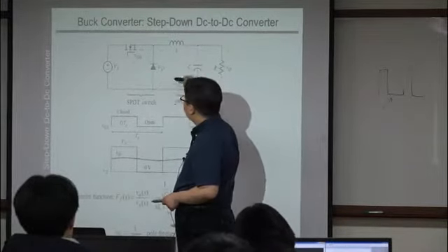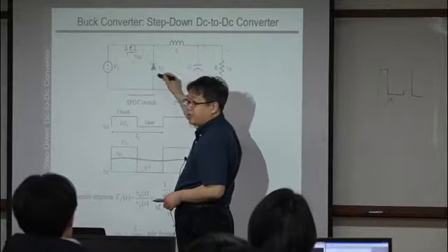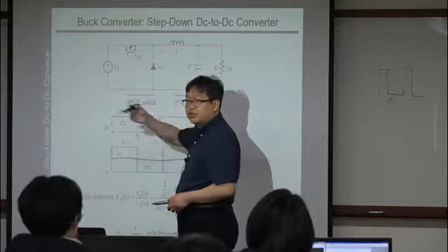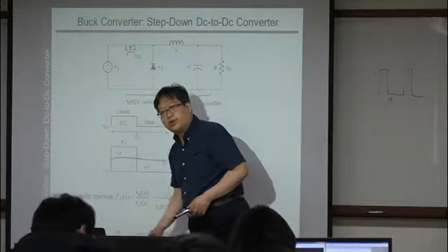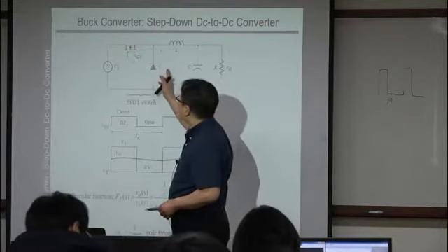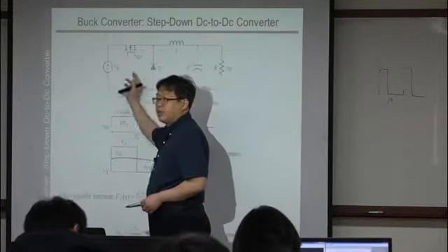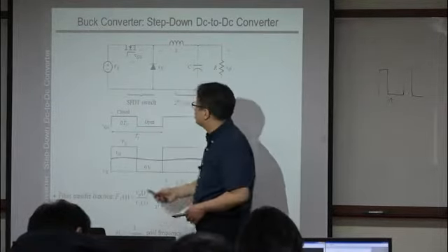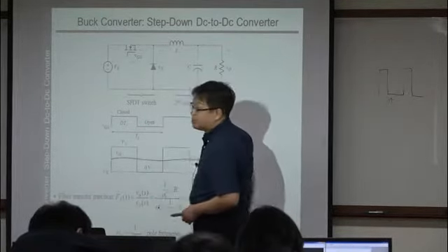I mean, you should apply, for example, a Schottky diode or a fast recovery diode. If you use a very slow recovery diode or a general purpose diode, then eventually your entire power stage will generate heat because of the reverse recovery energy. So this is a very important component in real applications.